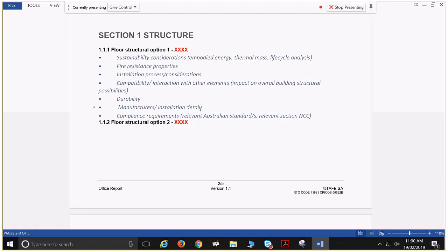When it comes to details, let's say you're researching concrete and you go on a website called CCA, Concrete Cement Aggregates Australia, a really good website. There'll be details about how reinforcing is included within a concrete slab, the correct coverage, the correct distance from the edge, bar size, things like that. There'll be a detail cut through a slab, and you go, that's a really good detail.